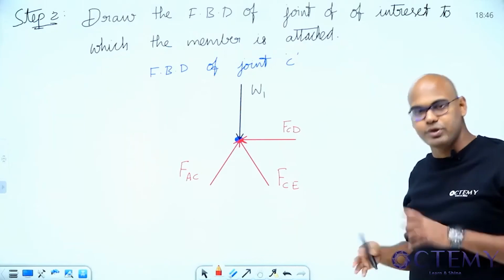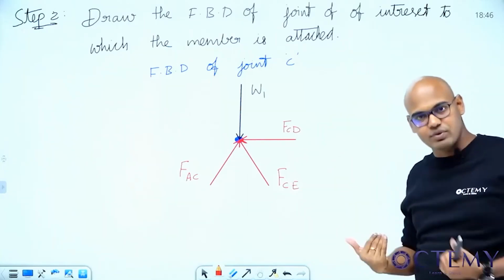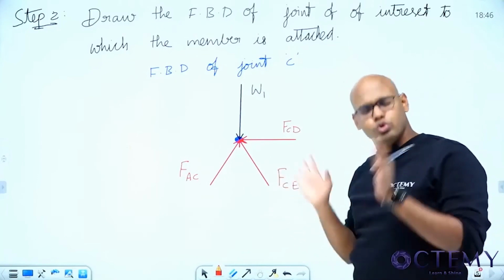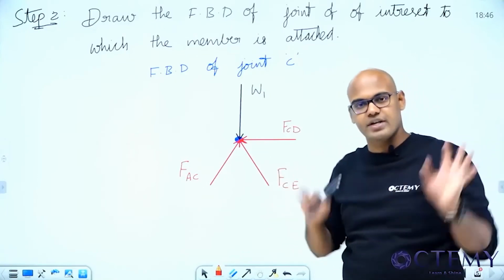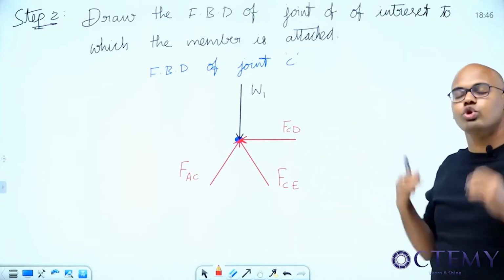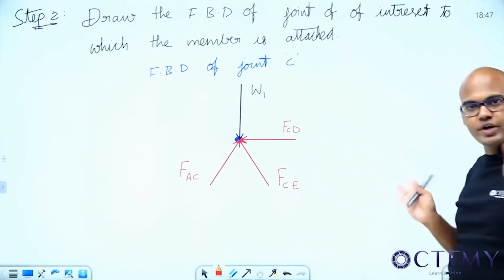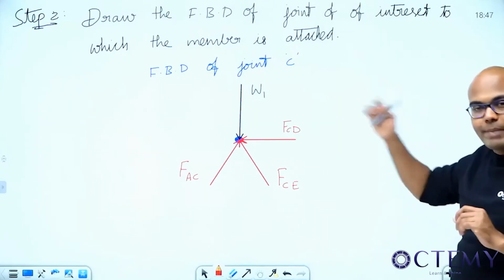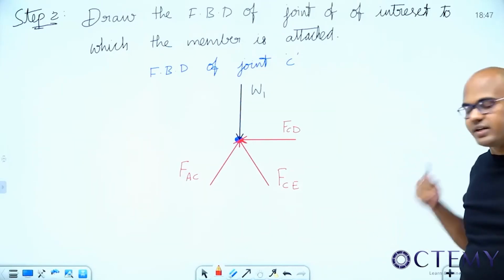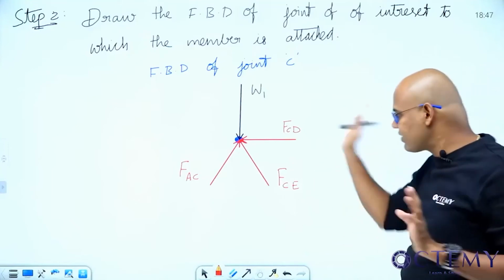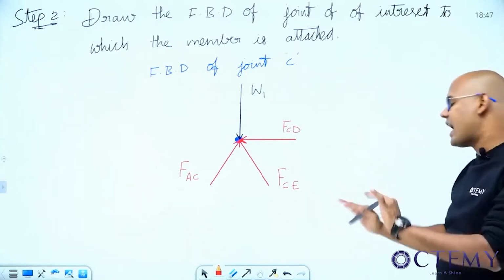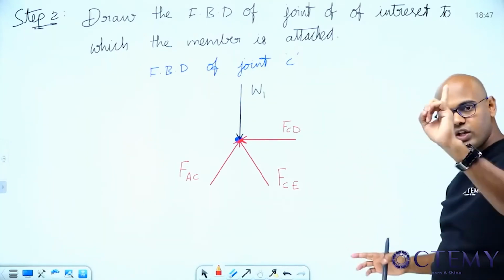In the exam, if you take something and then get plus or minus, you will get confused about what is happening. Don't have anything, just take towards the joint. If it is coming positive, yes, my assumption is correct, it is towards the joint. If it comes negative, no, my assumption is wrong, it is away from the joint. That's it. No need to come back and check what I have taken. Follow the same convention. Or if you take always away, you can, but only follow one notation.